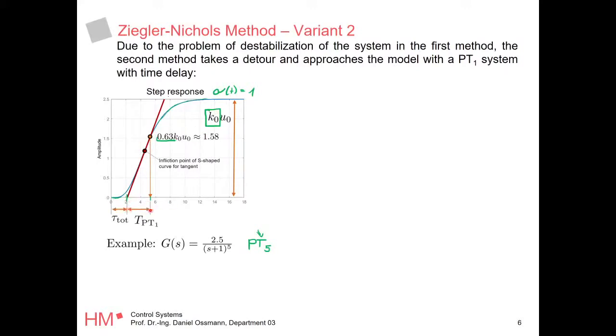So this is your time constant. But the problem now is, okay, it does not really start here. It starts at 0 because we put in the step here at 0. So we say, okay, this is simply a pure time delay. In this area, from here to that cutting point between the tangent and your x-axis, nothing has happened, and we delay our system response.